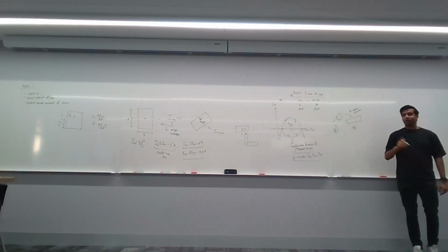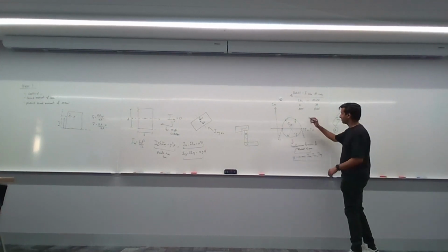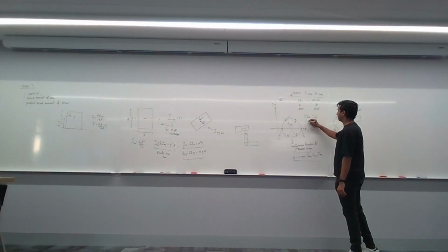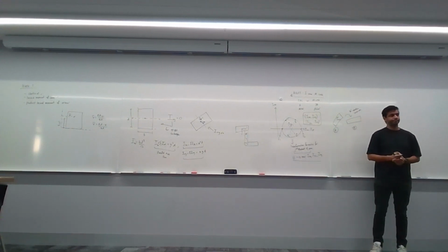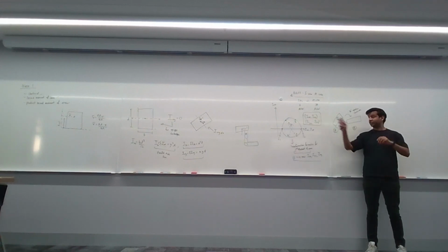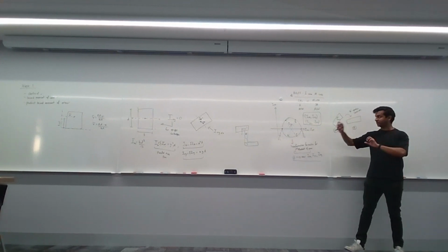Okay? Now always remember the points that you're actually plotting on your Mohr circle for any given system are IXX and IXY, and IYY and negative IXY. These are the coordinates that you plot on your Mohr circle. The coordinate that corresponds with IXX is the positive IXY. The coordinate that corresponds with IYY, for the x value, the y coordinate will be negative IXY. Those are the coordinates that you plot on your Mohr circle.